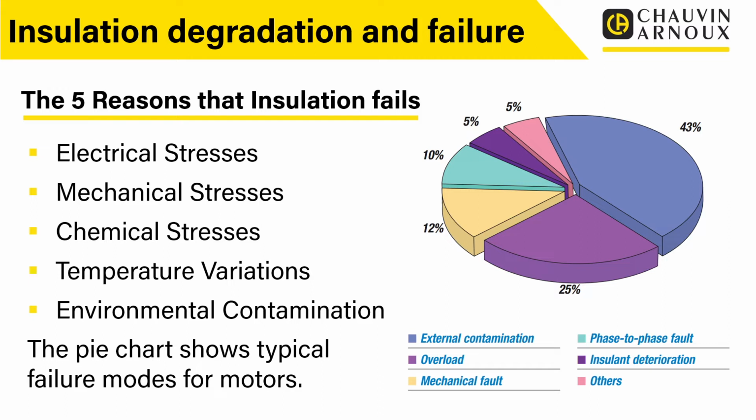So again, there are a lot of reasons why insulation can fail. And obviously, common sense dictates that keeping your motor dust-free, dry, clean, away from any oils, contaminants or coolants and things like that is good practice if you want your insulation to last and a long life for your motor. So in any preventative maintenance system, we try to keep away from that.